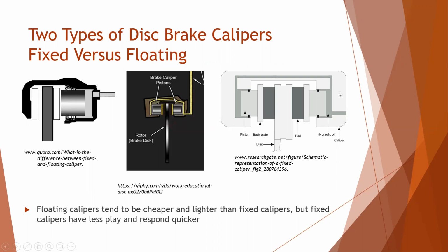This is another image of the fixed caliper on the right. As a note, floating calipers tend to be cheaper and lighter than fixed calipers, but fixed calipers tend to have less play and respond quicker.